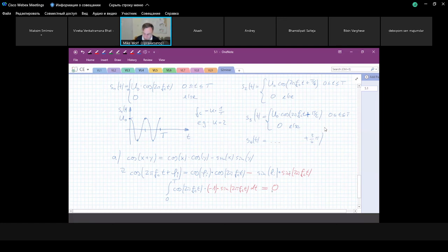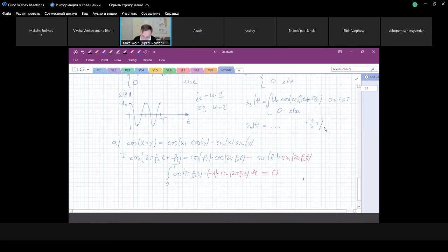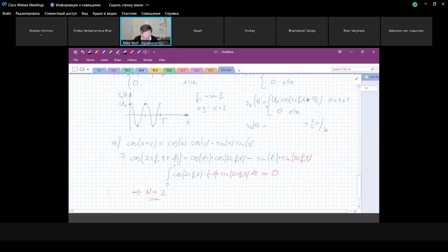And of course, we can mathematically describe all 8 signals just by a linear combination of a cosine and a minus sine wave. So our dimension of the signal space only needs to be 2, because we already know that we can decompose expressions like this into a cosine and minus sine components, and cosine and sine build an orthogonal pair.